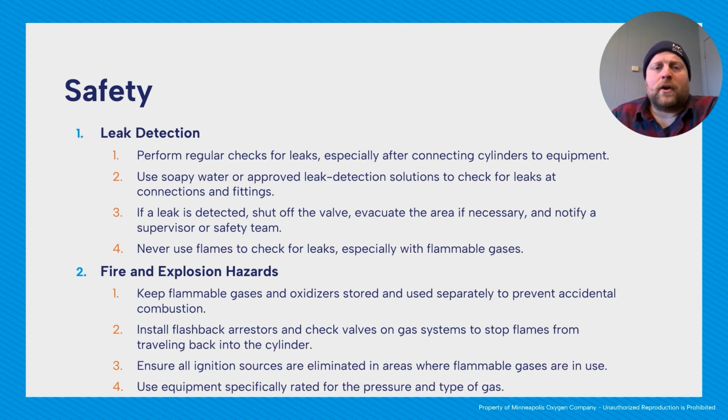All right, leak detection. We want to make sure we check for leaks. There are a couple different ways to do this, but we want to do it regularly. I like to do it every time I hook up a new cylinder to either a machine or a manifold system. It takes 5 seconds, and at worst, you're going to prevent yourself from wasting gas that's leaking out.